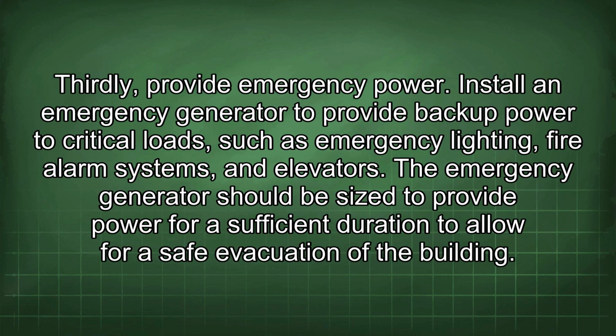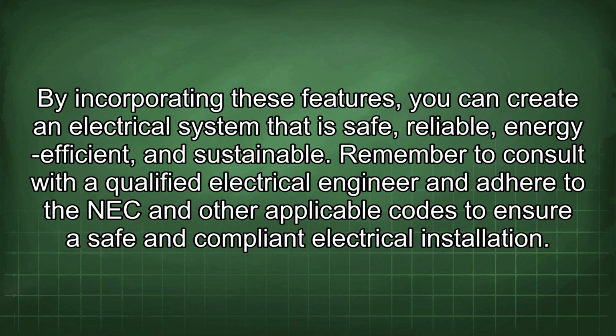Thirdly, provide emergency power. Install an emergency generator to provide backup power to critical loads such as emergency lighting, fire alarm systems, and elevators. The emergency generator should be sized to provide power for a sufficient duration to allow for a safe evacuation of the building. By incorporating these features, you can create an electrical system that is safe, reliable, energy efficient, and sustainable.